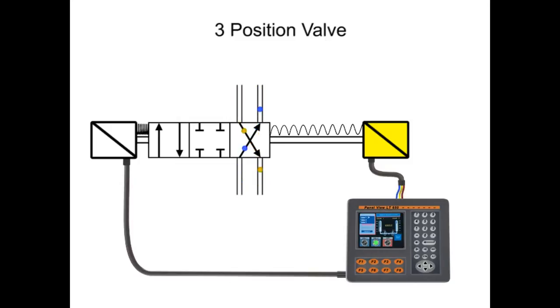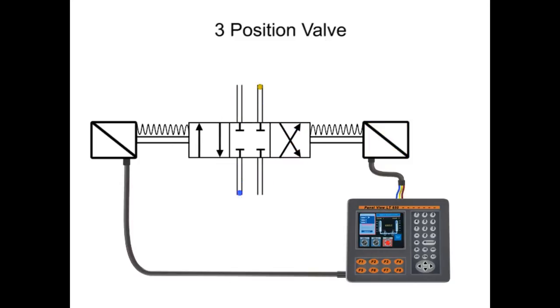Anytime both solenoids are de-energized, the valve spool will spring to center and stop the fluid flow. Therefore, a three-position valve requires a maintained electrical signal for its operation. As before, energizing both solenoids at once may cause damage to the valve or to the system. To prevent this from occurring, electrical circuits should be designed to make it impossible to have current on both solenoids at the same time.